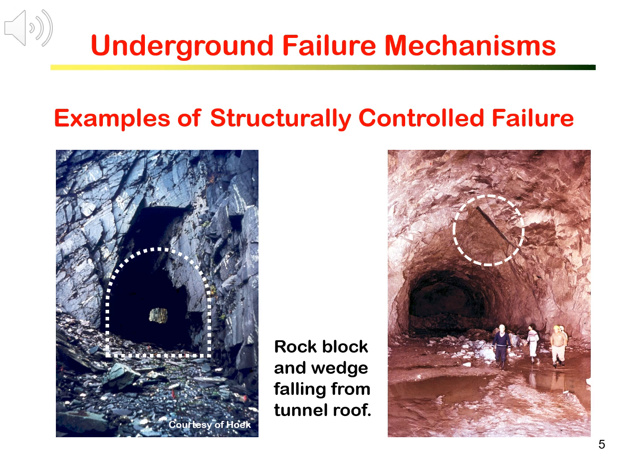The tunnel roof is now stable because the blocks are now interlocked and are not able to fall. On the right photo, you can see a wedge just fell down from the roof with broken pieces on the ground. Again, those failures occur because of existence of joints and fractures. The failure is a structurally controlled failure.